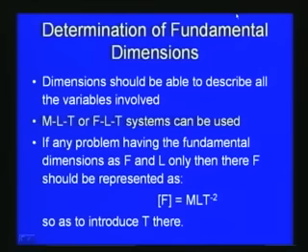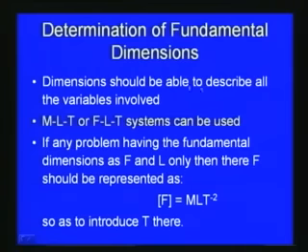And then the other important point is we have to decide the fundamental dimensions which we will be using. In the Buckingham pi theorem methodology, the dimensions should be able to describe all the variables involved, either M, L, T, mass, length, time, or FLT, force, length, time systems can be used. Depending upon the case, we can use MLT or FLT systems, and if any problem has the fundamental dimensions as F and L only, then F should be represented as F is equal to M L T to the power minus 2, that means mass into acceleration, force is equal to mass into acceleration.